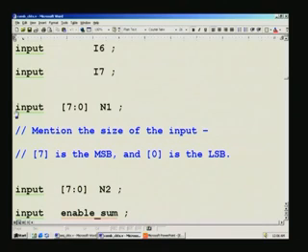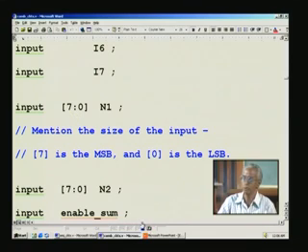And coming to this statement, you notice that N1 is an 8-bit number, which we have already covered, and we will touch upon it when we go to the actual assign statements that will follow suit here. And MSB, as I mentioned, is 7, and that is the first thing that should be put here, right. This is a prerequisite here, right. If you interchange, there will be lots of confusion. It will interpret as MSB, so you will have lots of problems.